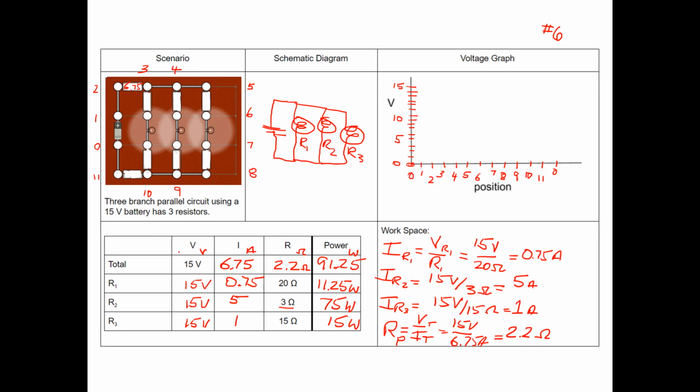Down R1, I'm going to change colors on this just so we can see a little bit easier. Let's go pick a good color. Hey, so I picked this light blue. Right, down R1, I know that there's 0.75 flowing through this light bulb, which means on the other side, 0.75. Means we have 6 amps flowing through here.